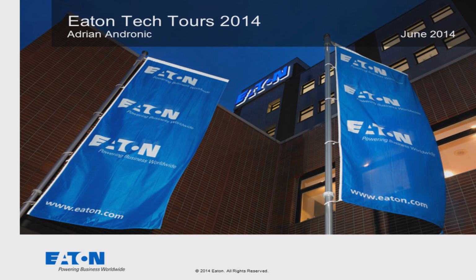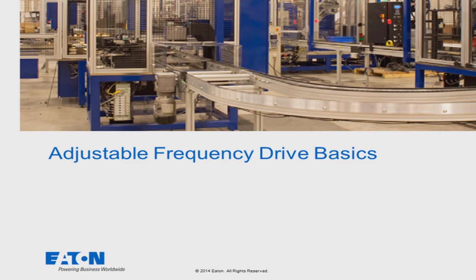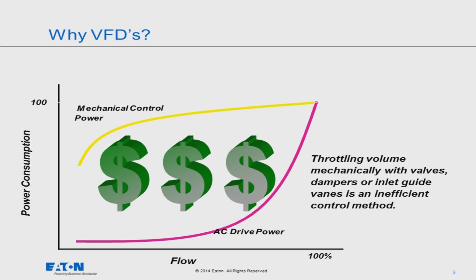Why VFDs? Can anybody tell me why we're looking to use VFDs? The main reason basically is energy savings. Why? If we're using an example for a standard application where we are controlling a flow, the classic one will be with what? So we have a motor that is powering a pump, the pump is pushing the flow, okay?